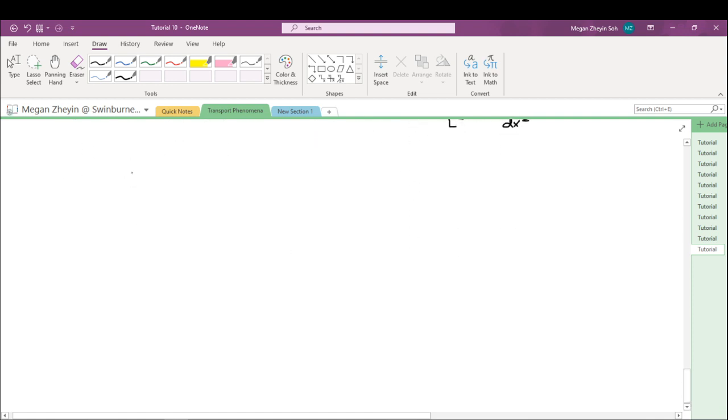So substitute everything in, we should get, okay, I'm not going to rewrite the equation from F, but I'll straight away put this in: C0 over L squared, d squared y over dx squared, minus U0 C0 divided by L, dy over dx, okay, minus kc (1 minus epsilon) rho P equals 0.